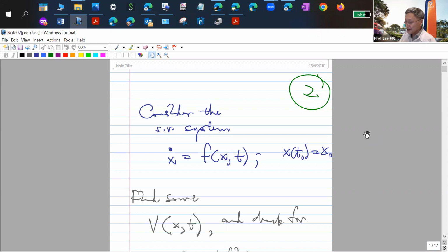All right, so remember what the Lyapunov method said. You write down your system in state variable form. As I reminded you, state variable form is exactly this: you tell me whatever your state variables are. If you tell me you have 3 state variables, then you better be able to write down your x1, x2, x3 signal on the right-hand side, no derivatives. It can be with all kinds of nonlinear functions, all kinds of time variance, doesn't matter. But you must be able to write x1, x2, x3 on the right-hand side with no derivatives. Then x1, x2, x3 must appear on the left-hand side with first derivative only. So that would be a state variable system.